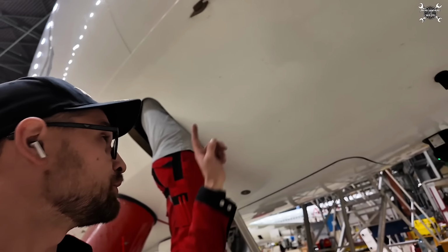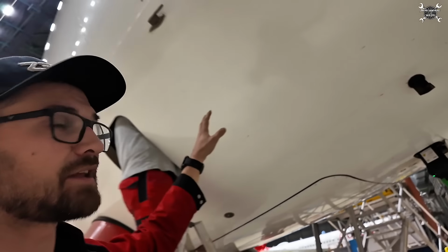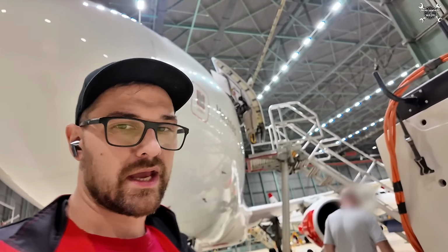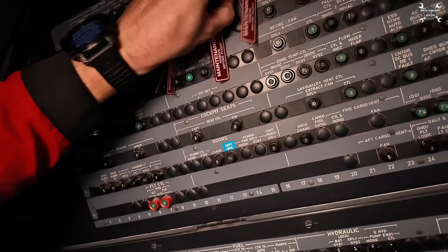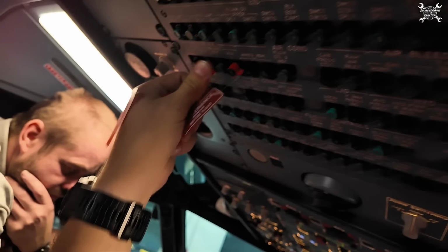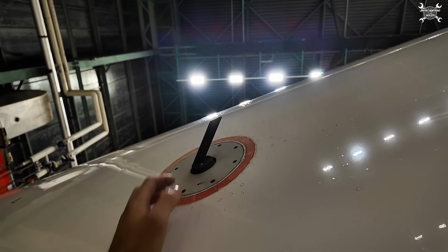There is one more CB which we pull inside of the right avionic bay. That one is to prevent deployment of the RAT if during the test we're gonna lose electricity. Because since we are reproducing a flight and we will suddenly lose the electricity, it will automatically deploy the RAT. But we want to avoid this, so as a prevention, we pull one more CB. And as a last thing, we will close all the CBs which we pulled before the test. And as well, we put the angle of attack probe back to normal position.